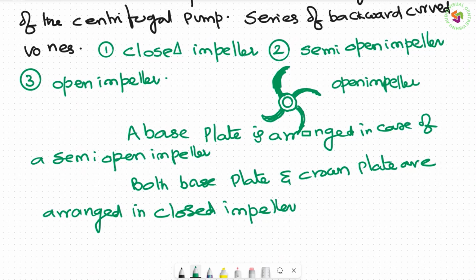If, in the case of a closed impeller, how it looks like, there will be only two plates, one above the other, but inside actually the vanes are there. There will be openings, through which the water will be coming out. In the case of liquids that are clean and have no debris, for houses and water supply, we use closed impellers so that the water will be guided properly and naturally the efficiency will be higher.